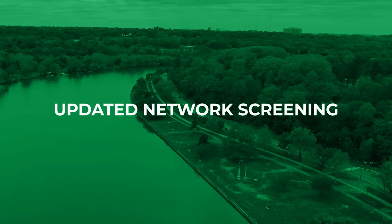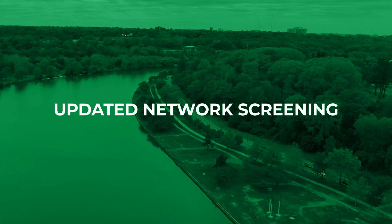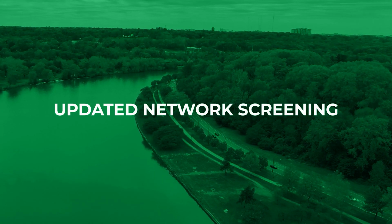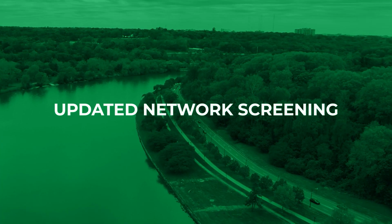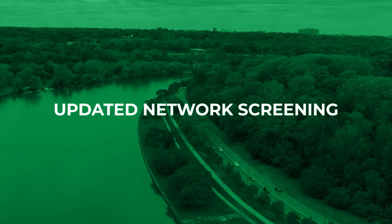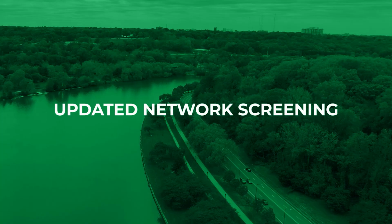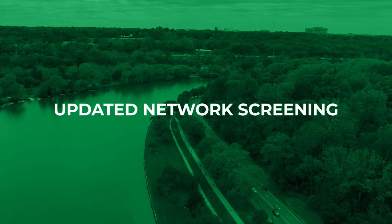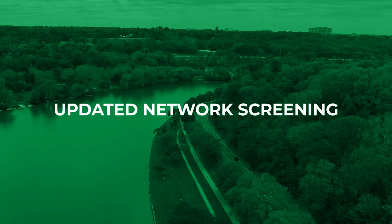Now that you know the basics about the HSM and network screening process, let's talk about what PennDOT's Highway Safety section has done and how you can use it. PennDOT conducted our first network screening in 2017. In 2021, we conducted a second network screening using updated data, new sites, and newly developed SPFs for collectors. This screening was the first to include freeways and ramps. The 2021 network screening accounted for crash severity for the first time. For greater consistency statewide, we also used a new source, census data, to determine urban and rural area types.